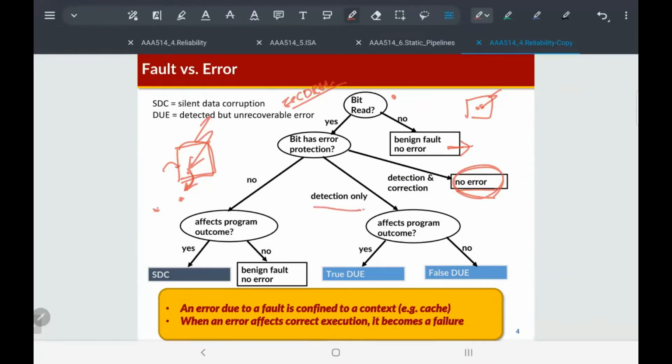Actually, double errors can be detected, but these double errors cannot be corrected with our ECC DRAM. The error is detected, but not corrected. In this case, the errors can be harmful, but we can also distinguish by the result of our applications. If the detected errors change the output of our application, then we can say it's harmful.